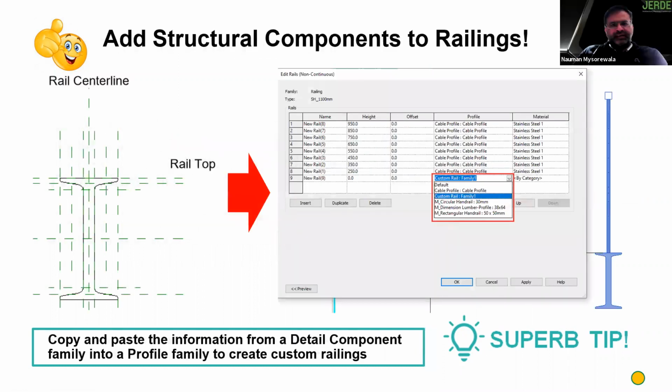Yeah, Rina, I use this trick a lot for elevators, just simple elevators when we are in schematic design. I make it a dynamic length, so I can select how tall that cut line is and how far below it goes too. So you can still see the elevator and the pit and everything. That's an awesome tip, Nauman.